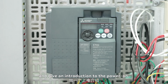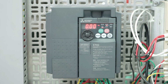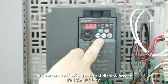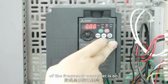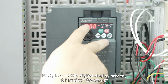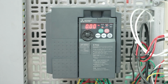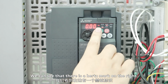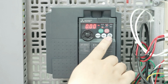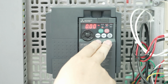Now let's power on and give an introduction to the power on. Okay, it has been powered on now, and we can see that the digital display screen of the frequency converter is on. First, look at this digital display screen, which is used to display the current parameters of the motor. We can see that there is a Hertz mark on the right. When this Hertz mark lights up, the content currently displayed is the magnitude of the frequency.